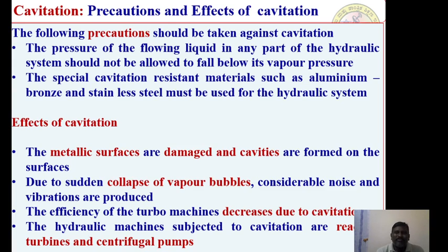Cavitation is nothing but an effect where the pressure of the water may fall below its vapor pressure, and by that time there will be a formation of vapor bubbles. Due to the sudden blast of these vapor bubbles at a position where the pressure is very high, they will create some cavities on the inner surface.